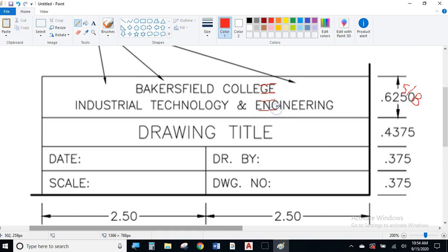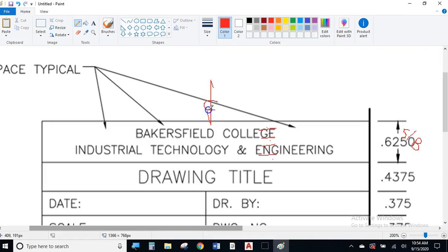And then you have your 1/8 inch text, and what you have here is 1, 2, 3, 4, 5 equal spaces, 1/8 inch each one. They are centered right here. That's the center line for all the text. If you do this with multi-line text, you won't have an 1/8 inch between the two pieces of text. They're kind of squished together. So best bet for here is to draw some guidelines all the way across, 1/8 inch down, and you can copy them 1/8 inch apart.